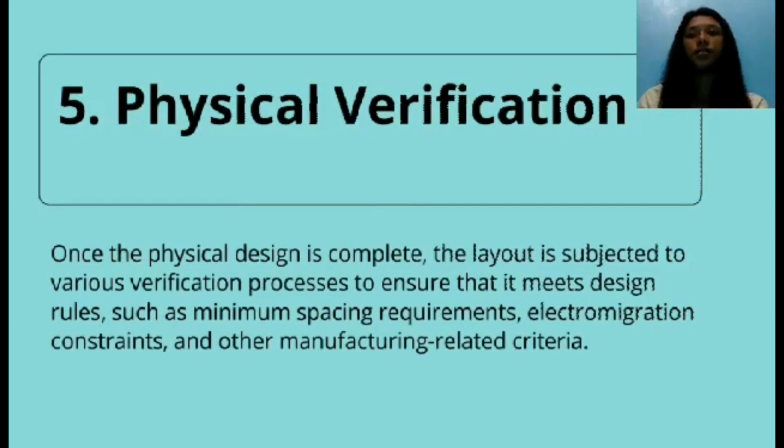And lastly, the physical verification. Once the physical design is complete, the layout is subjected to various verification processes to ensure that it meets design rules, such as minimum spacing requirements, electromigration constraints, and other manufacturing-related criteria.